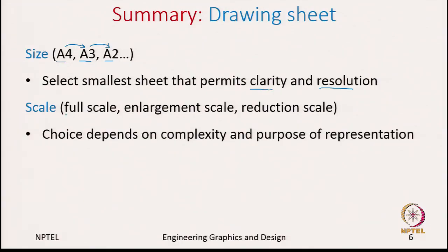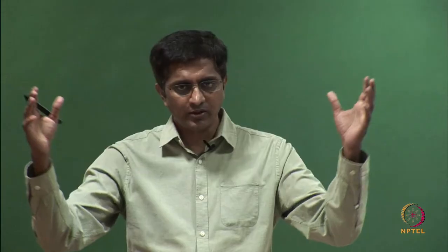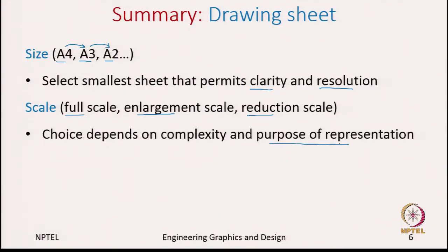Similarly, for the scale we looked at 3 different scales: a full scale, which means 1:1, an enlargement scale where the drawing size is much larger than the object, and the reduction scale where the object is much bigger but your drawing paper is small. And again, this choice depends on the purpose of representation and the complexity of the object.